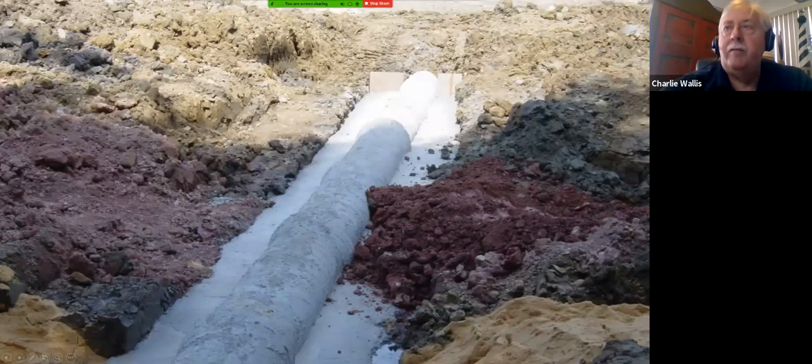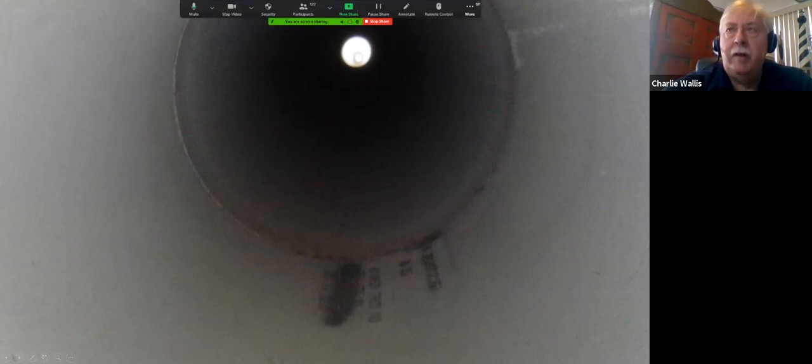Here's another photograph of a spillway pipe with the concrete already set, and this would be the impervious core. Just downstream of the impervious core is where the filter diaphragm, which is composed of sand typically, would be constructed. It's important that a spillway pipe have a straight alignment, that there be no settling or displacement of the joints, and everything should look smooth and have a good appearance to it.